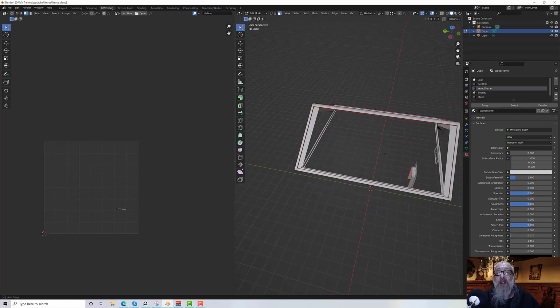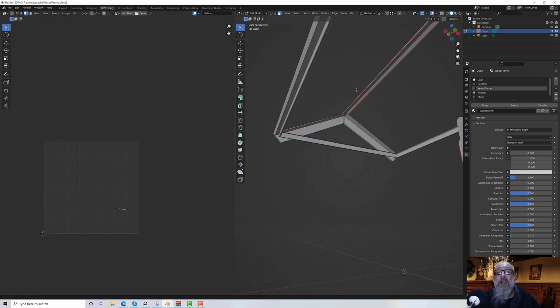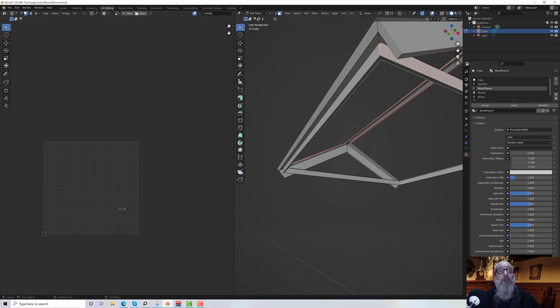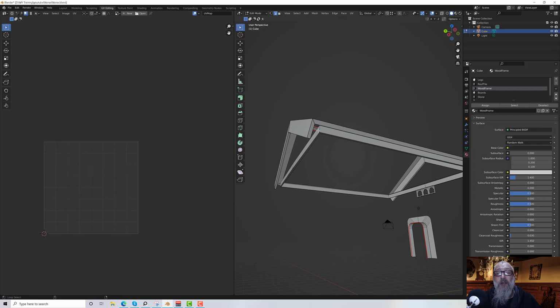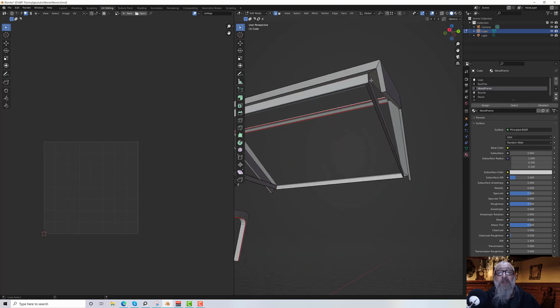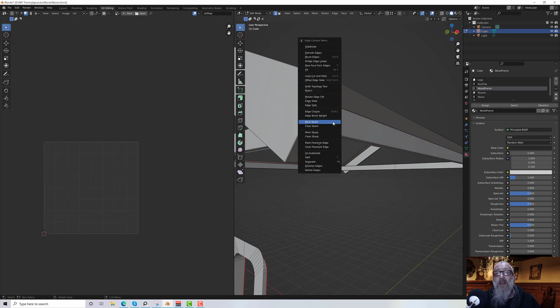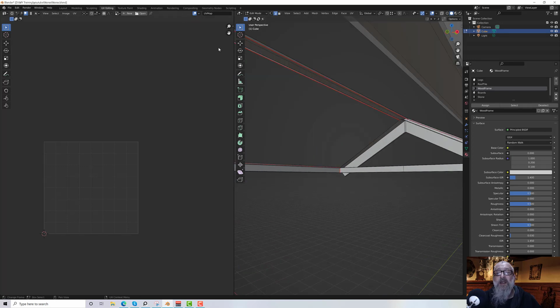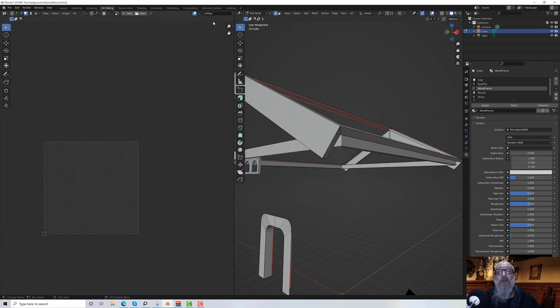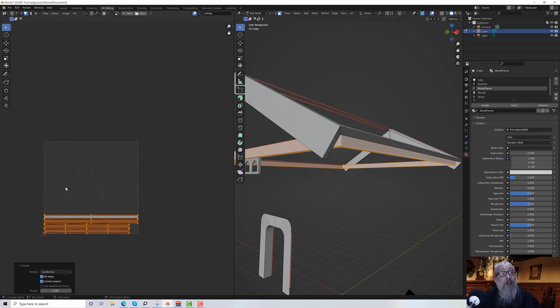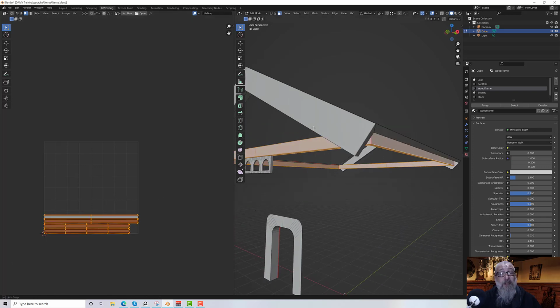Okay, that's separate to the roof. So if I go in underneath, I can do the same as I did below. So just mark each edge, each corner rather. So I'm just selecting with Shift Alt, and then right click and mark as seam. Oops, let's come away from that. Select, Control L, A in the 2D view, right click and unwrap, and then hide those. Whoops, again in the 3D view.